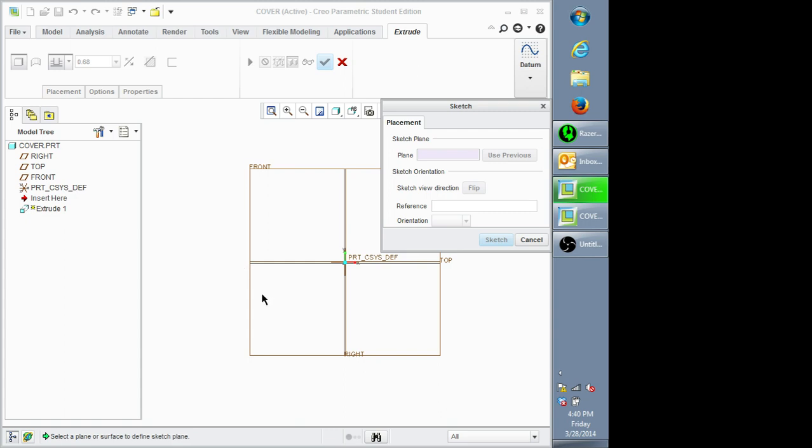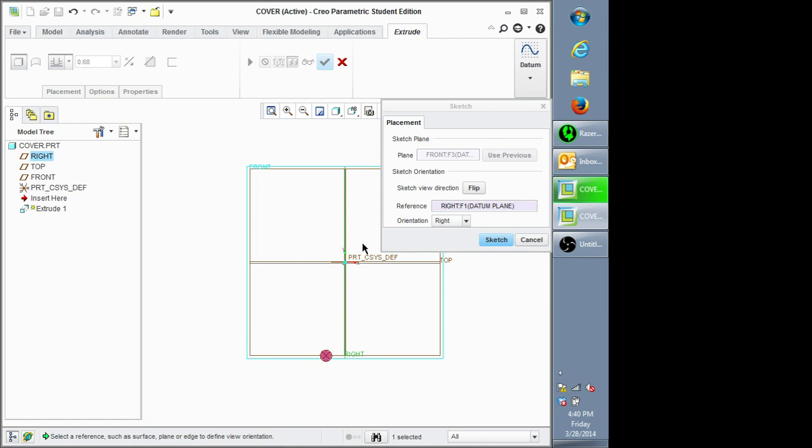When you have a bigger computer, it takes a bit more time to track, whereas here you can just right click right in front of where you're looking and go into the sketch plane. We want to sketch onto the front plane because that's the view we want. Right now, since we only have three datum planes, it doesn't matter which one appears in this box. It will matter when you have a lot more datums, and Pro will automatically select whichever it feels fits.